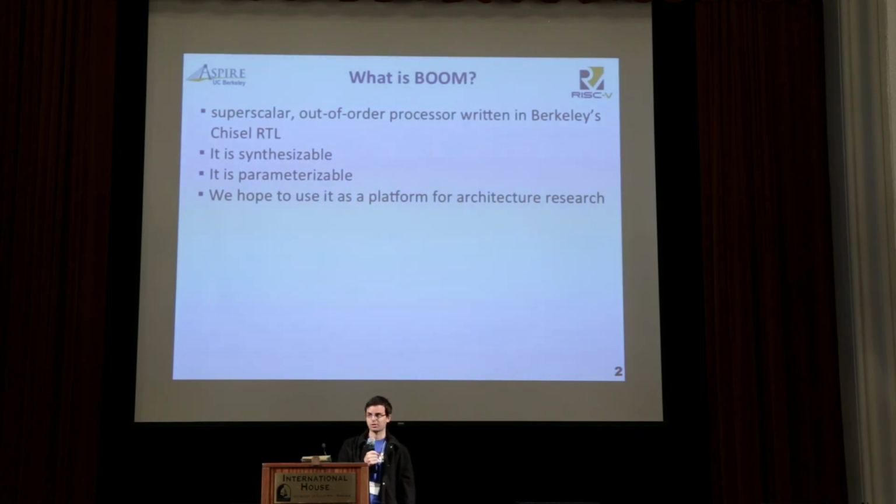So Boom isn't a single design. It's really an entire space of different Boom designs, and you can search this space to try and find the best Boom design, but actually you can find really a Pareto optimal curve of best Boom designs, trading off performance and area or power. So this is something that we hope to use as a future platform for architecture research, where Boom can be the base design, and maybe you can either use Boom to extend it to do different things, or you can compare Boom to a different microarchitecture. So that's what Boom is.